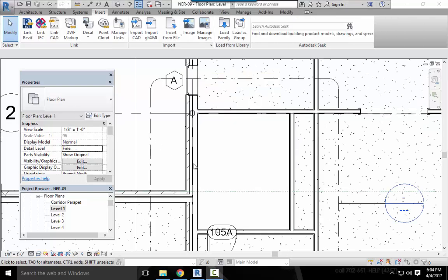All right, so we're going to start adding detail to the model by adding components, or adding interior design, as the book would like to call it. Adding plumbing fixtures and furniture. To begin, you'll have to knock out the less glamorous but all too important task of adding bathroom fixtures. In the project browser, go to level 1 floor plan, which we're at. Floor plan, not ceiling plan. Zoom in on the lavatory area and turn off the thin line mode as shown in figure 9.35.